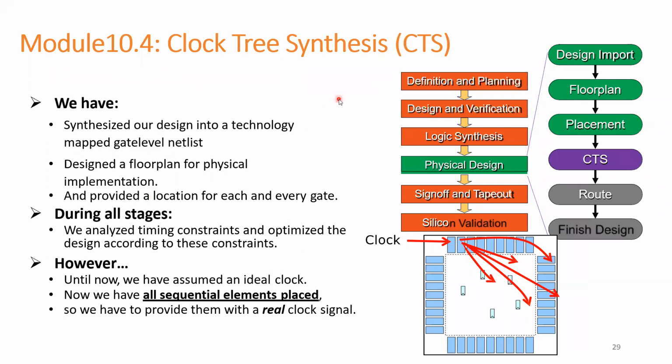So coming to clock tree synthesis. Here you can see the clock source. The clock will be built to each and every sink pin of the flops. From clock source to sink pin, we call it clock latency or insertion delay, and that should be within the limits. The clock arrival time delay difference between any two sink pins which are talking to each other will be called clock skew.